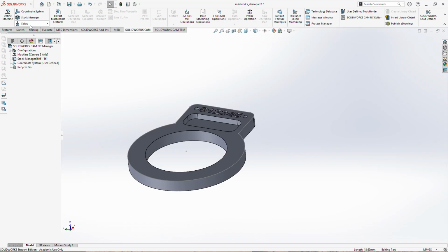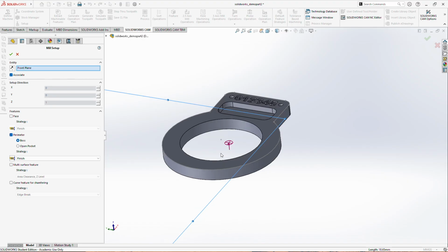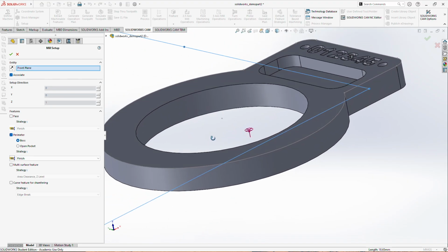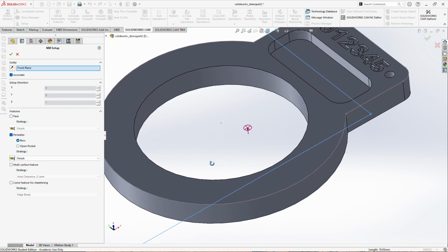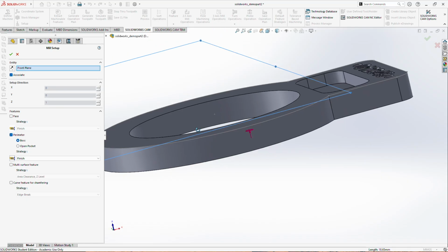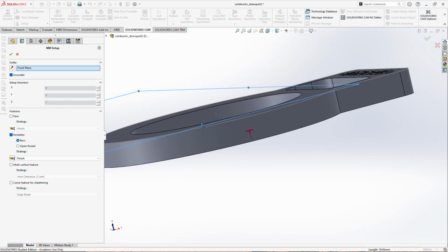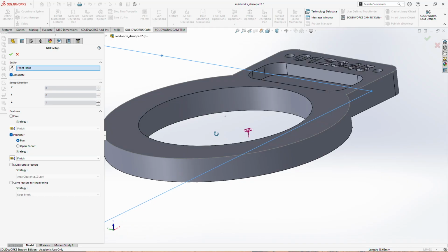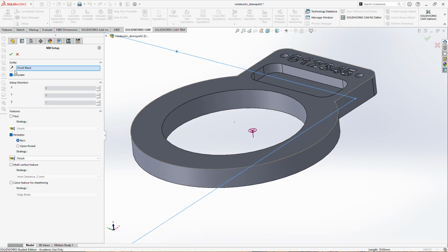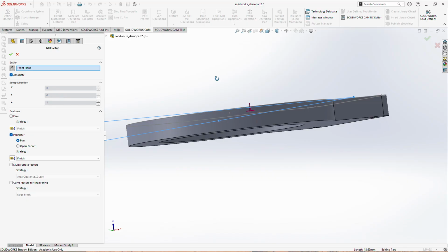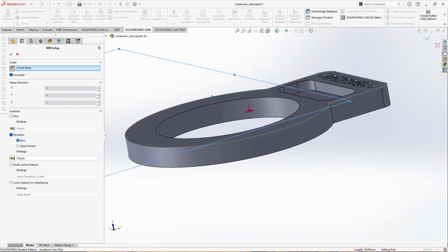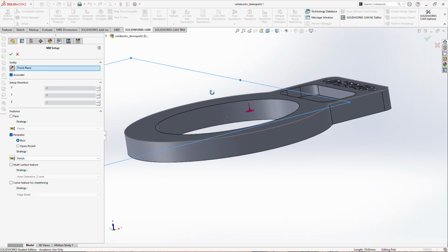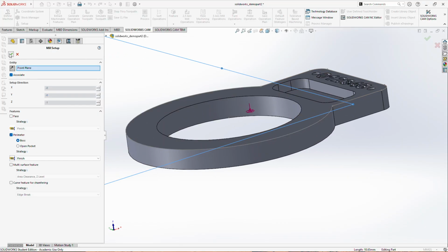All right, and then the last thing we have to do is press the setup button to set our machine configuration in the mill setup. What this does is it tells SolidWorks CAM the orientation of our machine. You'll see that there's this little red arrow, and it should be facing the same way as your mill spindle. You can see that it's not, right? The arrow is pointed up from the bottom, but I need it to point down as if my mill head is coming down towards my part. So I'm just going to press this little flip entity button. Now you can see that the arrow comes down and lands on the top of our part, like the mill head will lower on the Carvera. That matches our mill orientation, so we can press the green checkbox.